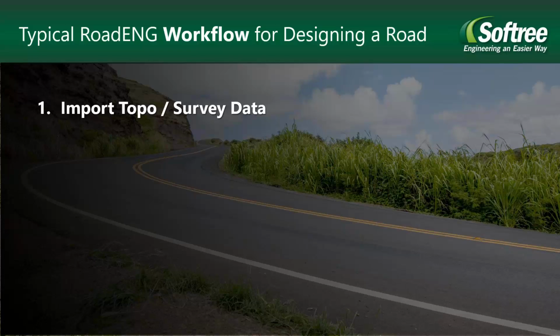Okay, so let's get started by reviewing a typical workflow for designing a rural road. We start by importing our topo. The terrain module is used to import and verify survey data. Possible data sources include total station, LiDAR, or GIS maps, or file types that you might be familiar with, such as shape, DWG, DGN files, etc.